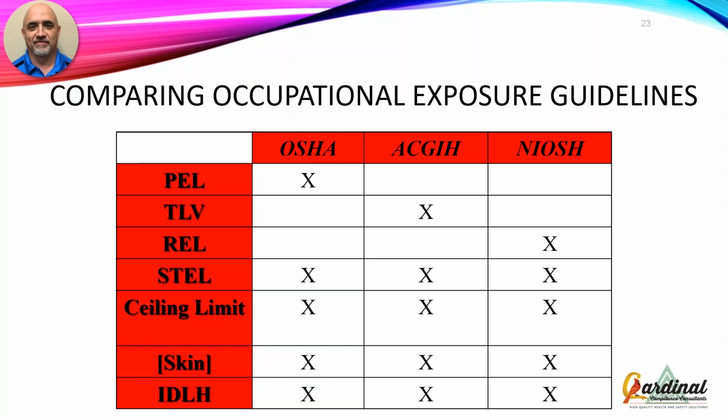And then I have IDLH. IDLH is the level that I can be exposed to for up to 30 minutes and still be able to self-rescue. Exposed to 30 minutes and still get myself out on my own. You have to understand what these limits are. IDLH does not mean, oh, I died. It could, but you have to understand this stuff. You have to understand where your permissible exposure limits are.